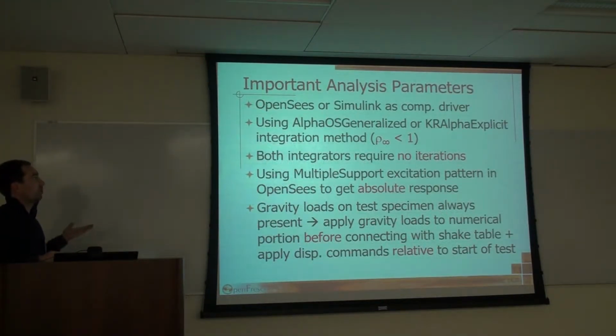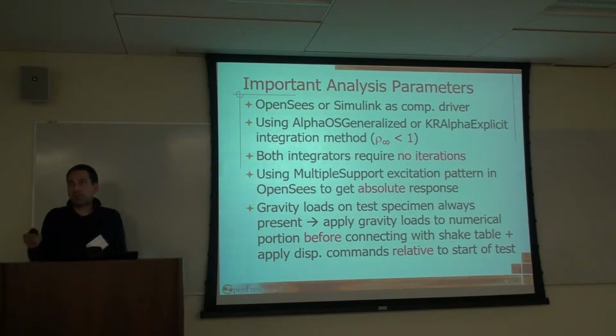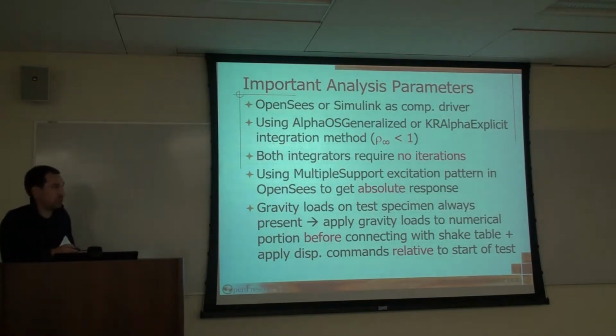Some other things that we need to consider when we do these types of tests: we can use OpenSees, and sometimes we use OpenSeesSP, a parallel version, to make this go really fast, or we can do it directly in Simulink as a computational driver, basically what Sean Gao showed. We can do this conversion, put everything into Simulink, and do it there, instead of having an interaction with actual finite element software. So we can do both applications, and we've tried both of these when we do these real-time hybrid shake table tests.